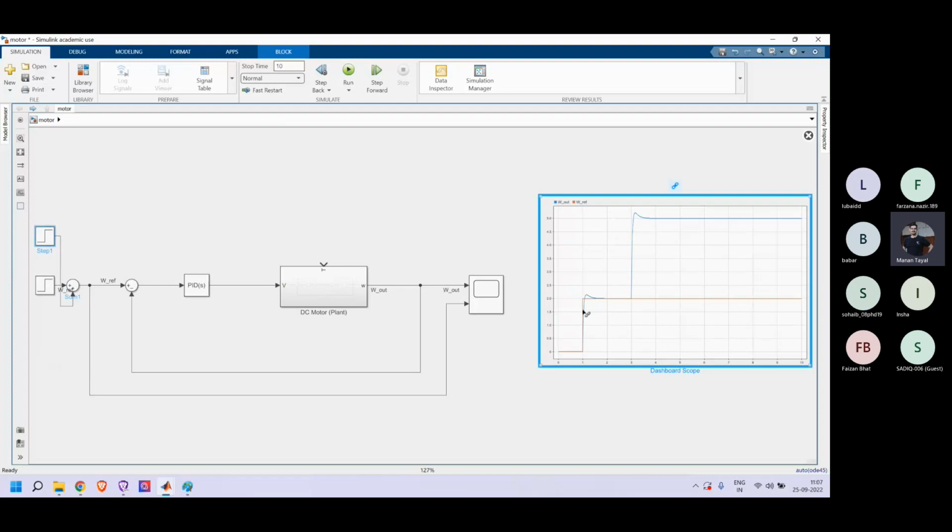So just to make you appreciate why this controller is quite good, this settles in 0.8 seconds. So I can change my inputs from the controller at a much faster pace. If my controller took say 2 or 3 seconds to settle in, I would not be able to get a good response in that way.